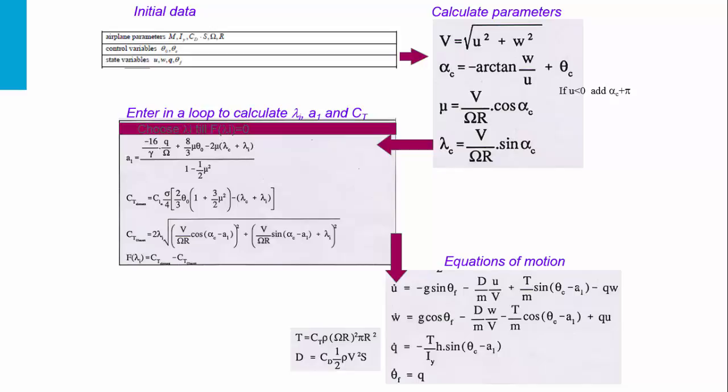First, you have to express the flapping longitudinal disc tilt. We already derived this longitudinal disc tilt. You can calculate it at every moment. And we have also derived the thrust in blade element theory and in Glauert theory.